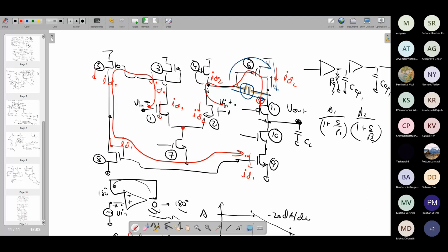They are different. In magnitude terms, we can still say, if you look at omega 0, or basically DC gain, and ignore all the capacitance, the magnitude will definitely be aligned, because whatever small signal current you are producing is the same. Suppose the signal is plus VD/2 on the positive terminal and minus VD/2 on the negative terminal, where VD is the net differential signal.